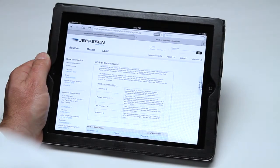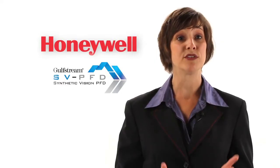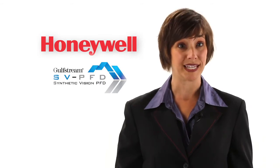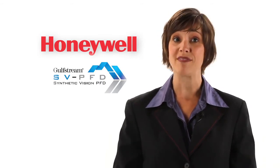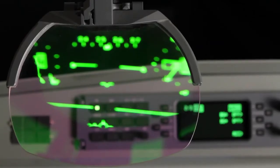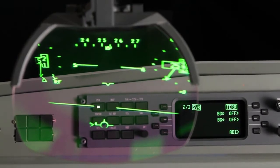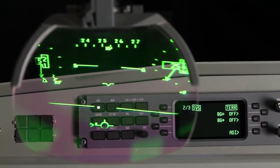Pilots must remember that the terrain display on the Synthetic Vision PFD is intended for situational awareness only and must not be used for navigation or terrain and obstacle avoidance. SVS is not a replacement for a HUD and must not be used as primary guidance for takeoffs and landings.